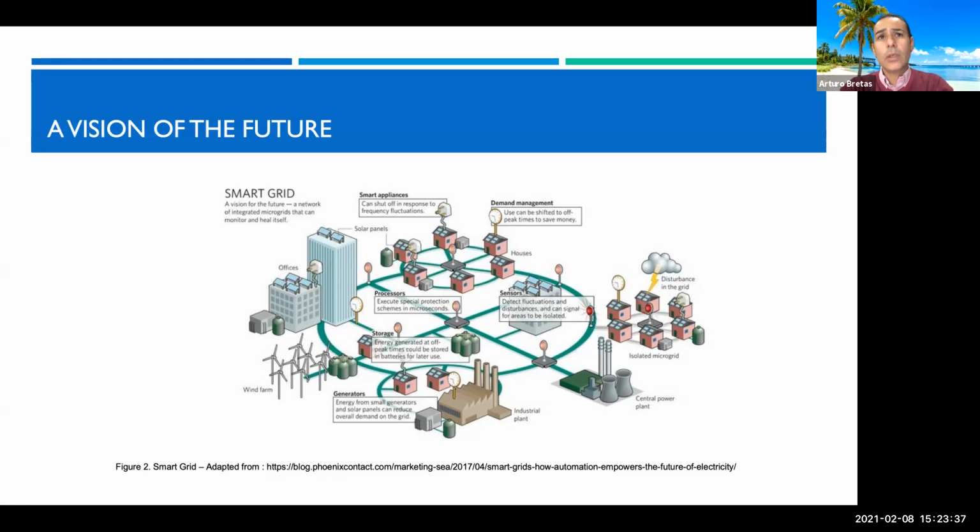So you have several different types of attacks that don't need to be only on what we call the smart grid layer, which is what one has been used to use towards real-time monitoring or state estimation, which are voltage measurements, power flow measurements, power injection measurements. But they can also be in other layers of the system as we know it, such as the communication layer, meaning denial of service attacks and spoofing attacks. So they can happen on these layers that so far are seen kind of isolated, but really are interdependent.